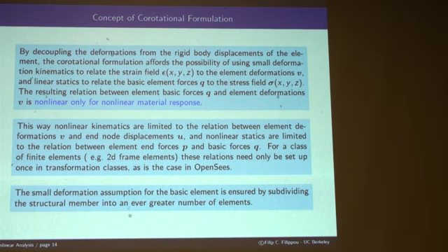Now, somebody may say, hold on here. You sound a little too cute. How do you ensure that the deformations inside the element are small? I ensure it by subdividing the structural member into as many small elements as I need.